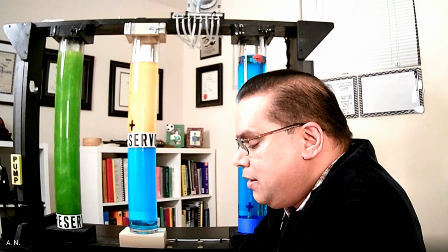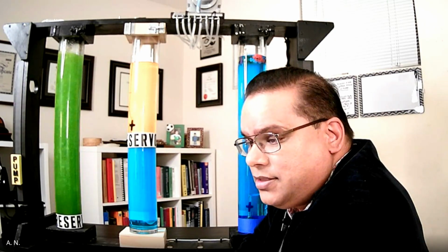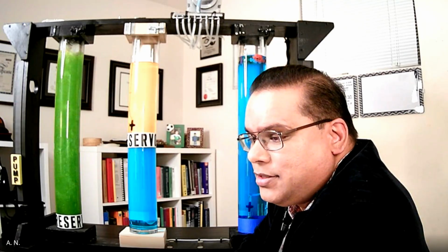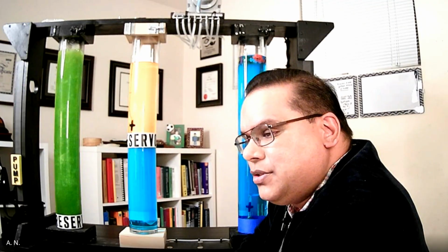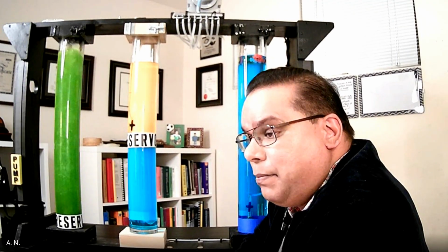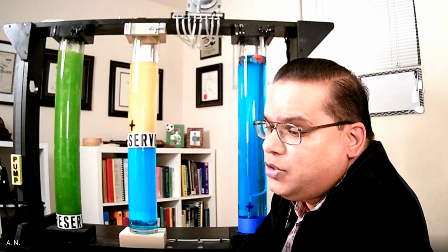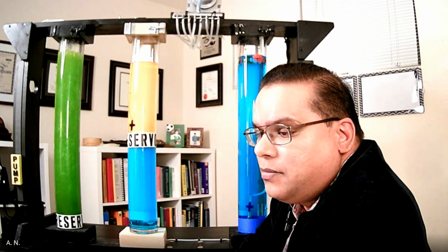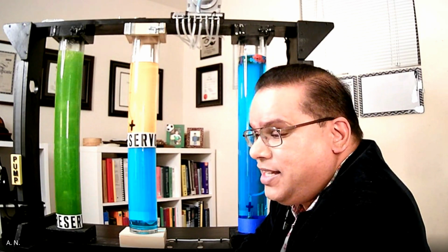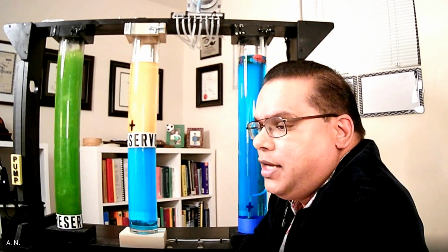So my challenge to you is to go back to your production engineer, show them this video, challenge them, and ask them to update their calculations. Make sure they don't use surface densities and constant pressure gradients, and ask them to better predict what's going on. Because I'm afraid if you don't do that, they're going to keep those calculations, and those calculations are going to be wrong, and you're going to have a wrong understanding of your pump intake pressures, and therefore your FBHPs, and therefore your reservoir and everything else, right?